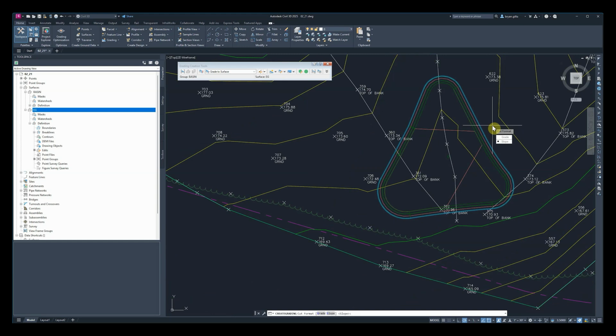We're going to use slope as our cutting format this time. And then for that slope, we're going to put in a value of 5:1. Once you've got that in there, press enter. And then for your fill format, press enter to accept our default of slope. And once again, we're going to maintain our fill to go with our cut. So 5:1. Press enter, and now we see we have all of this exterior grade to surface slope created for us.